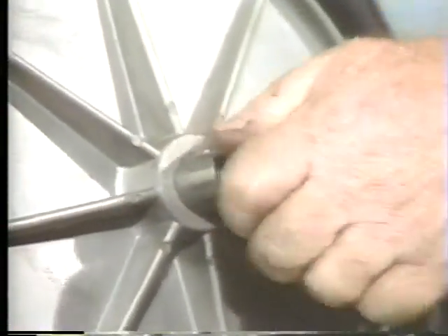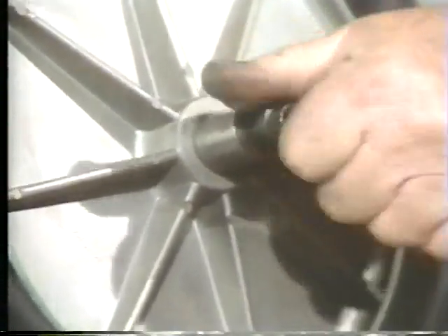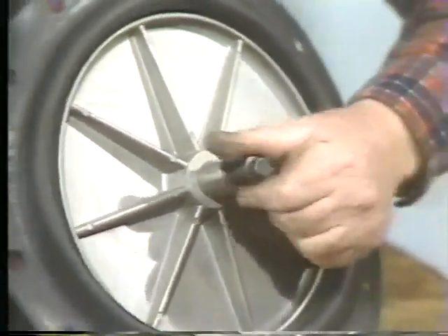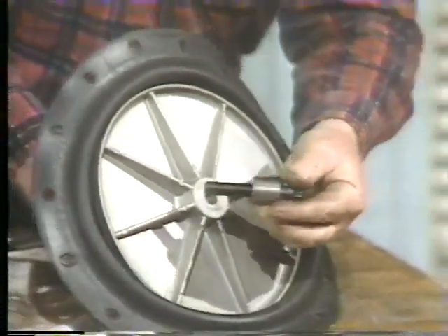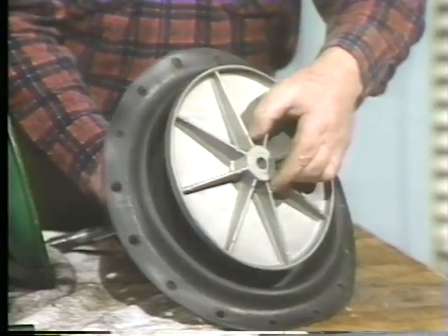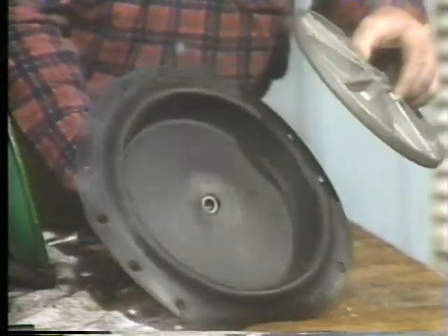The cap screw is screwed into the actuator stem to hold the entire assembly together. A metal spacer that is slid onto the cap screw during assembly limits how far the diaphragm assembly can move inside the diaphragm casing, as we will see when we describe how this actuator operates.